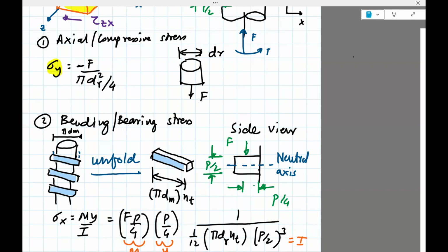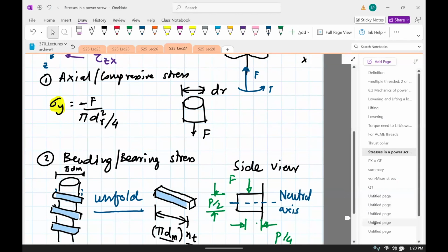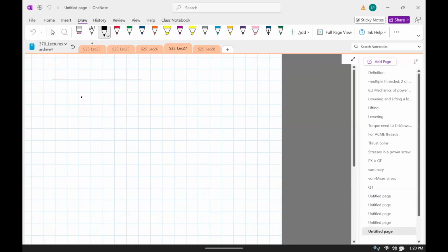You pull out one, you pull out the second one, you pull out the third one, and line them up. So unfolding it gives pi dm times nt. The number of threads times pi dm will give you the total length. Unfolding it, a better way to draw it would be...